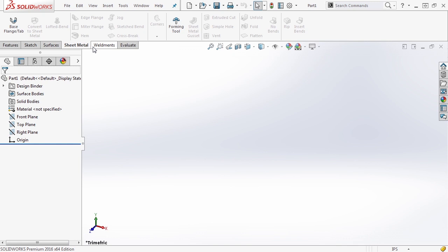First, we're going to start talking about sheet metal parts, and there are two main ways that you can start a sheet metal part. You can either create some sort of base. Now, this is going to be the base where you have a flat section and bent parts are going to start to come off of it. Now, in SolidWorks, when you're designing your sheet metal parts, you design them as formed or as bent. Then you can flatten them out and make sure that everything works how you expect it. And then you can ultimately end up with a flat pattern that you send off to be water jet or laser cut, stamped, whatever the case is. And that's how you get the end result for your bent part.